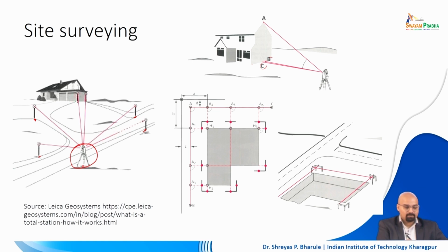So, the intersection of all of these points will give you the position of the total station which is there. Now, why is that important? To identify the location of total station from where your land starts, you can actually plot the first point, which is probably A in this case, right. So, this is probably your edge of the street or edge of your plot, these 2 black lines which are there, right. That is the edge of your plot which is visible in this example as here.